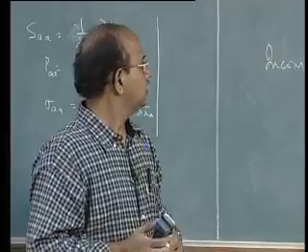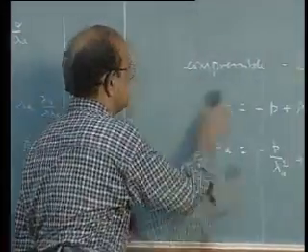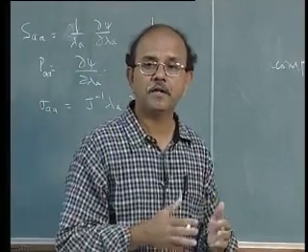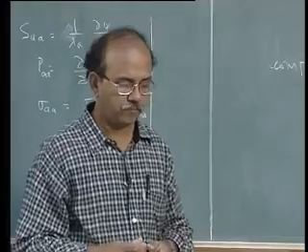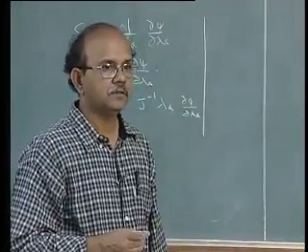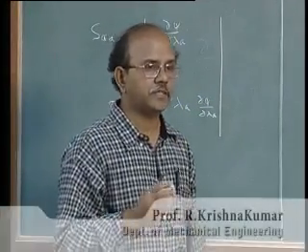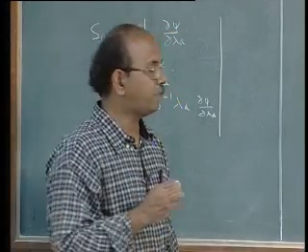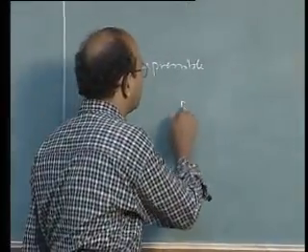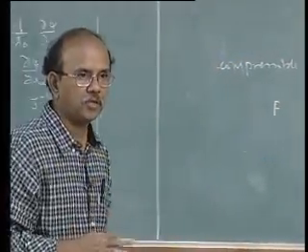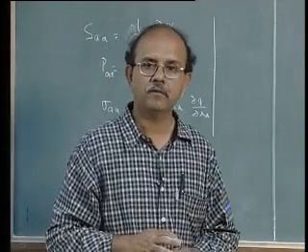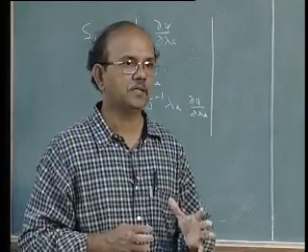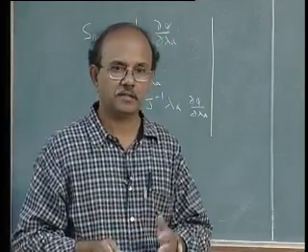So we now move into compressible elasticity. Again, a general compressible elasticity followed by isotropic compressible elasticity. One of the things that is done in compressible elasticity is to split F in such a fashion that we have a volumetric part and an isochoric part, in other words, a deviatoric part and a dilatational part.